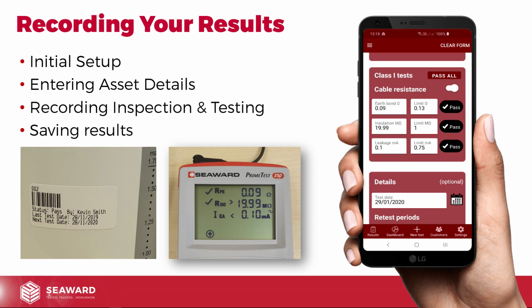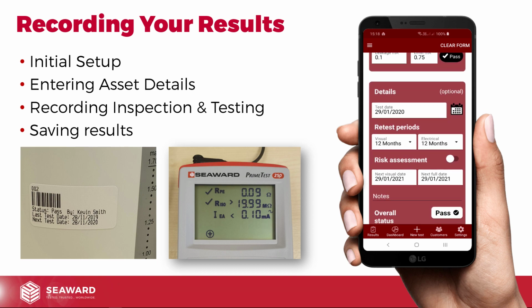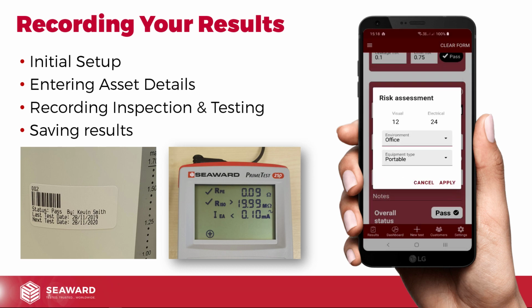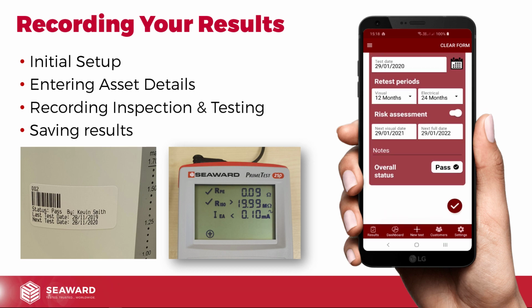Now the next bit down here is we can set the retest period. The retest period we can set in manually, or again we can tap the button and it allows us to do a risk assessment. So we pick the environment. In this case it was in an office, and the type of equipment is portable. So it's filled those in for us, and we apply that and it gives us the details on there. And then all I do is move down to the bottom and hit the tick.